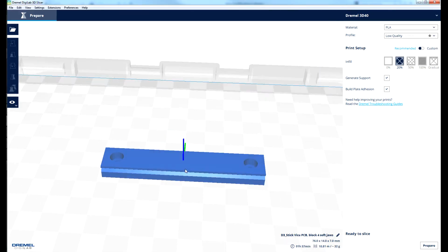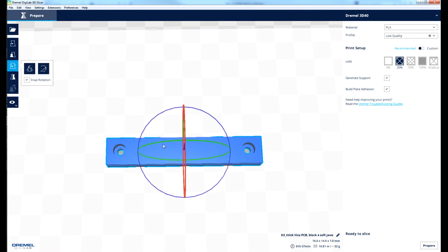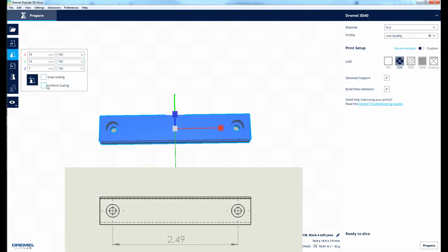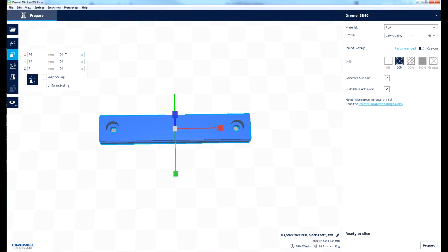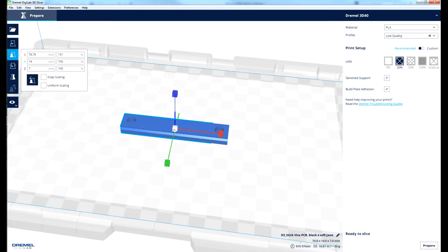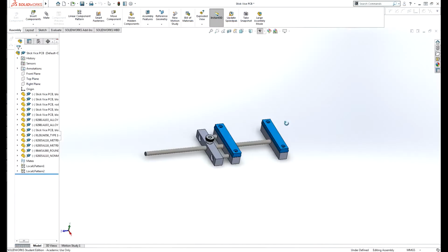This amount will vary based on the overall size of your part, its orientation, and again, the material that you're using to print. You'll find when printing screw holes, mounting brackets, or mating parts, they might not fit as you dimensioned or toleranced. Depending on your CAD design, you can simply scale your model here to compensate for shrinkage. Scaling can be done uniformly, so the same ratio across the X, Y, and Z axes, or just along a selected axis or two where the shrinkage is more prevalent.